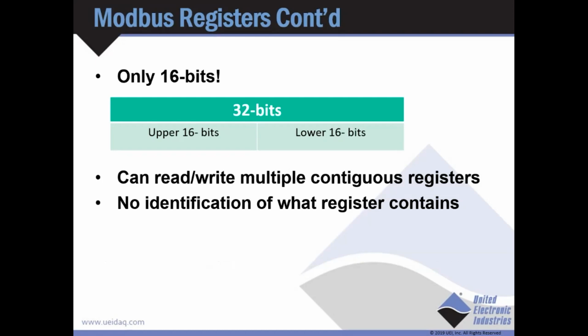It's worth noting, though, that not all Modbus servers represent the 32 bits with upper and lower, how I've shown it here, and sometimes it'll actually be swapped. So you'll want to consult with your Modbus device to see how it's sending the data.